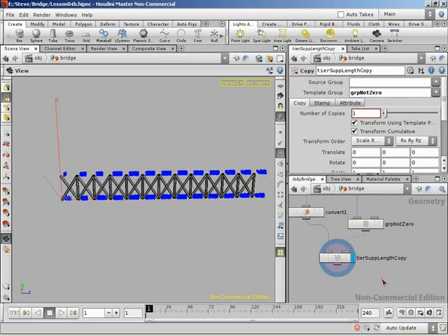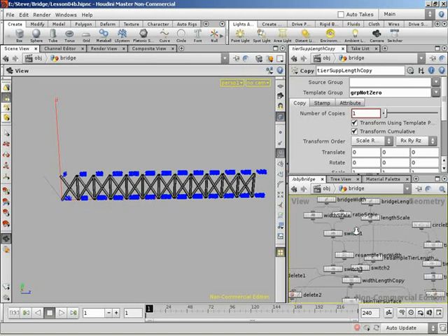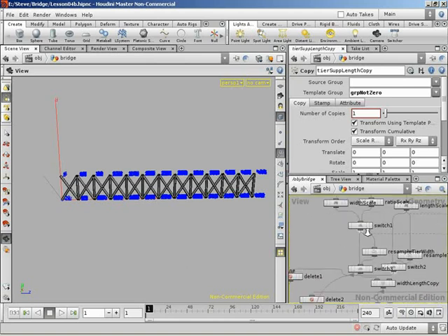Okay. So we jump up to our width curve where we switch here. I'm going to switch before we resampled this time. The reason is that resampling was changing the number of divisions based on our surface, on our tier surface, but that isn't going to necessarily be how many towers we have, and so we don't want to have the possibility of using this guy. Further up the network, when we start dealing with towers, we're going to be resampling up here to generate the right number of points for towers and things. So I'm actually going to branch off from this point.